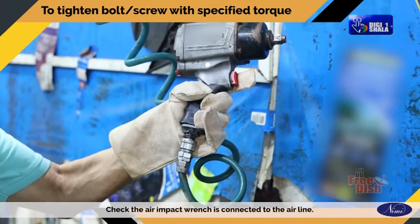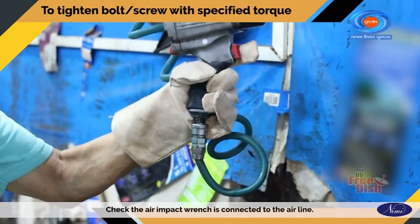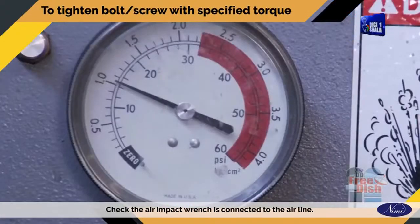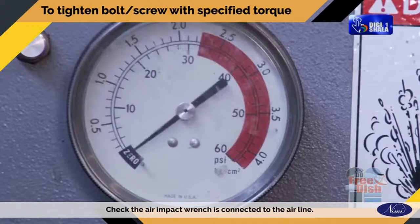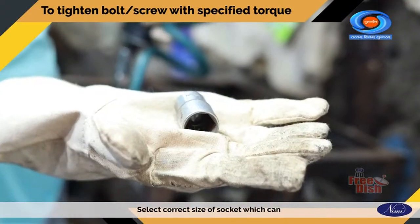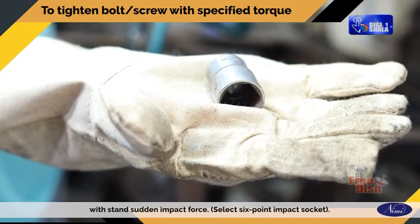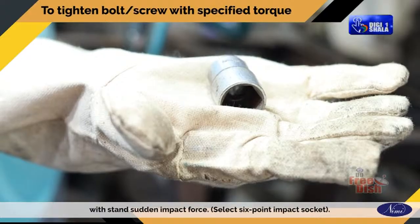Check the air impact wrench is connected to the air line. Select the correct size of socket which can withstand sudden impact force. Select a 6-point impact socket.